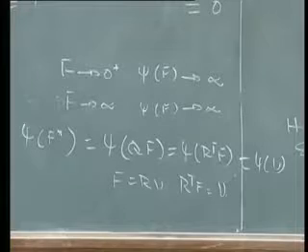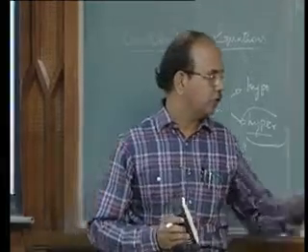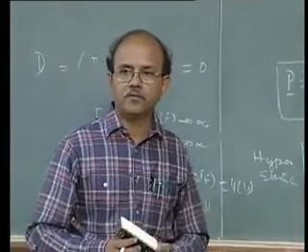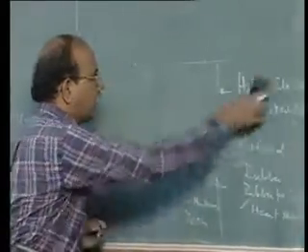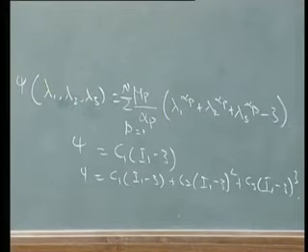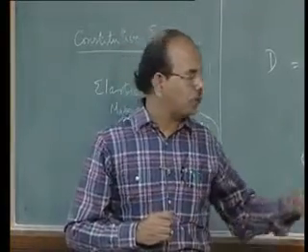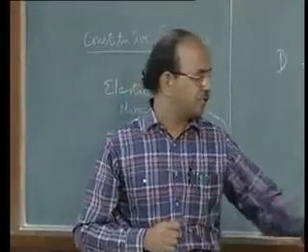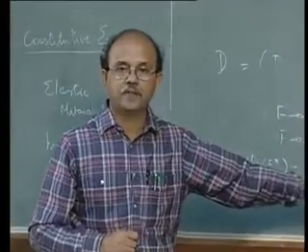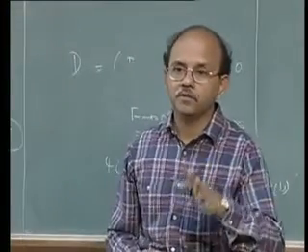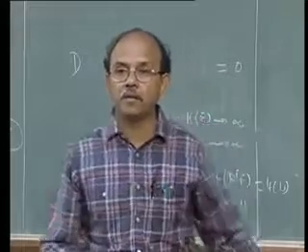Okay. Now before we proceed, we'll look at one more aspect of the material behavior and this objectivity, what we call anisotropy. The question that comes to our mind after looking at this is, what is the connection between anisotropy and objectivity? Or in other words, what we said here is that when there is a rotation, the rotation does not affect the behavior of the material, or the response is not affected by the rotation.